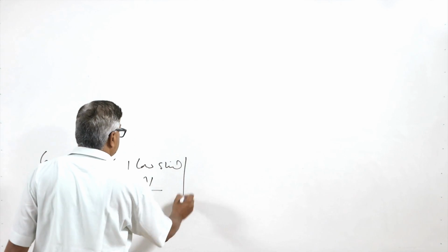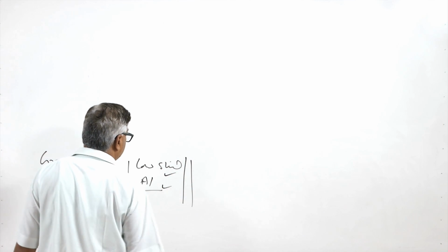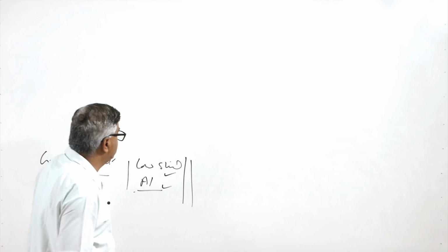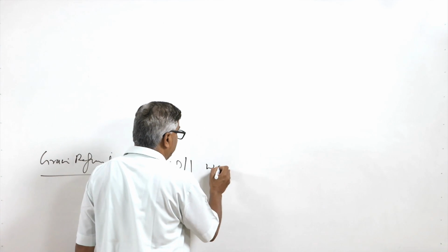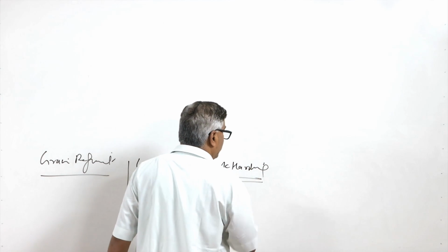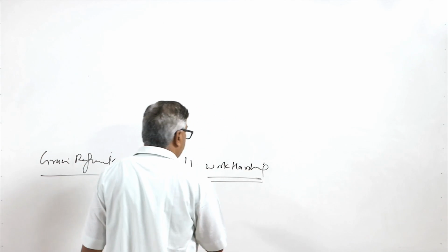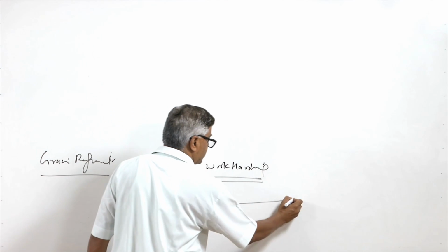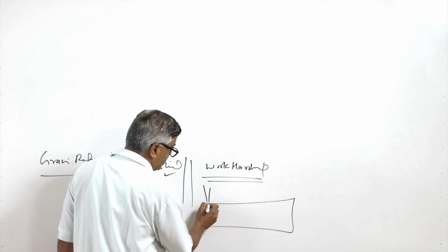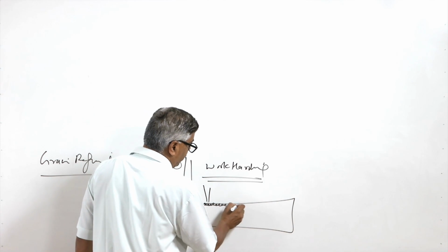But for these systems, like low carbon steel and cast aluminum alloys which are not heat treatable, basically work hardening methods are used. In addition to the work hardening methods, just for grain refinement, what we can do is apply an intense heat source so the surface layer melts, followed by rapid cooling.